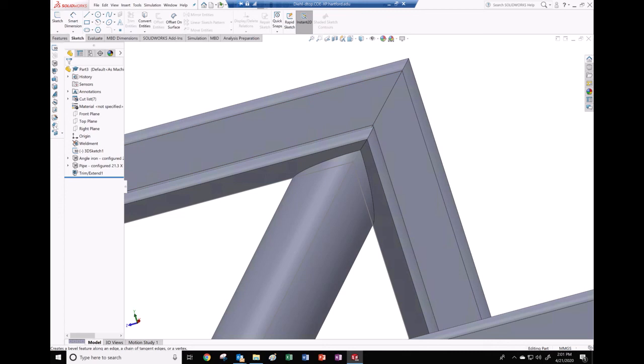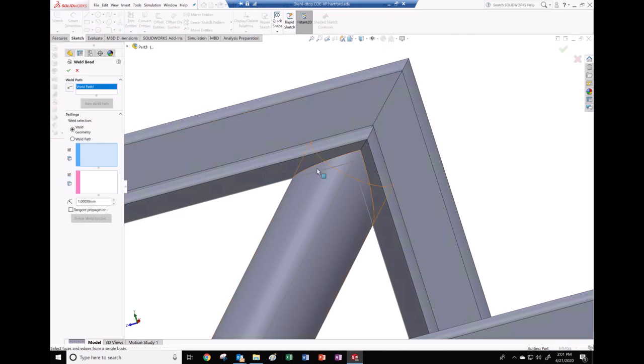You can see that it's trimmed the thing off, and you could also put little welding symbols inside here, like you could make it look like a weld bead. So we could pick it right here onto this edge, right in there, and all that's going to do, I don't think it's actually going to make a preview. Weld geometry. Okay, no, I see it right here. Let me clear this. I think you weld from here to here, and you can see there's the weld bead, okay?